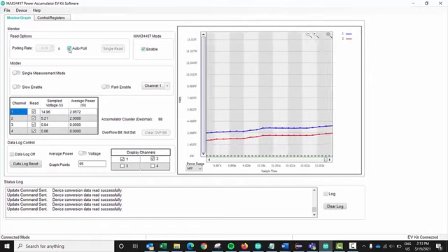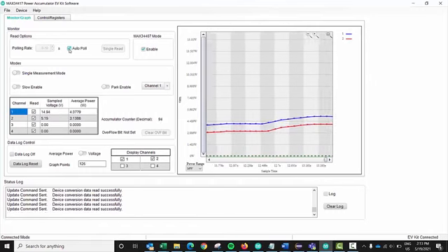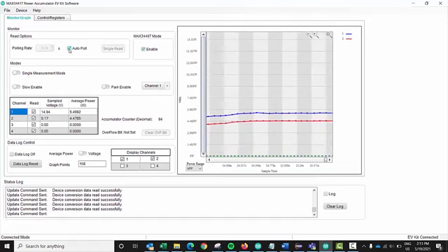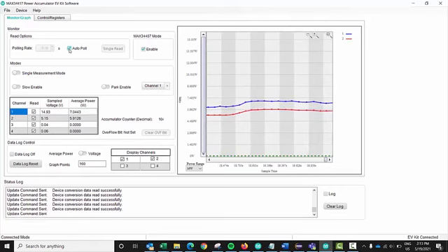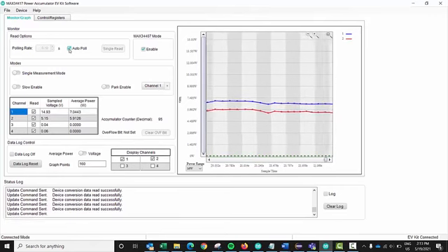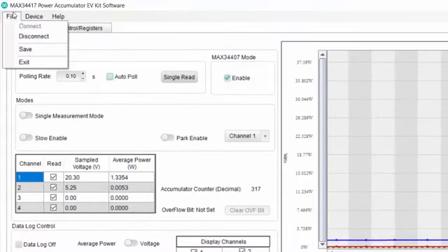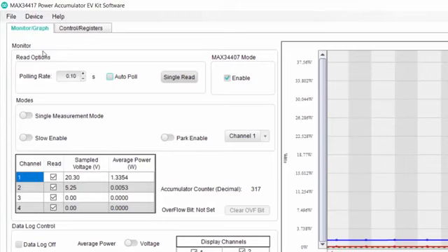With analog equipment, I typically start from the lowest input voltage and cycle through the full current range, then increment the input voltage and start again. I do this again and again until I reach the maximum input voltage. When you are done, go to File and save the stored data wherever you like.